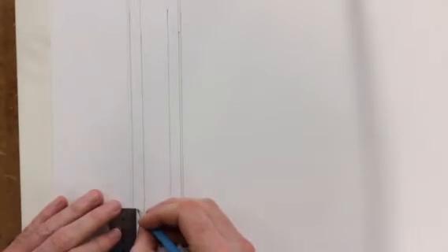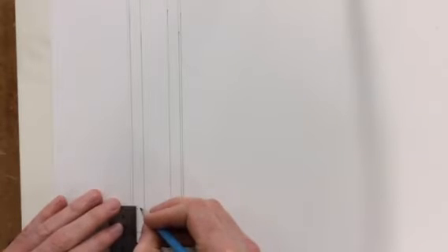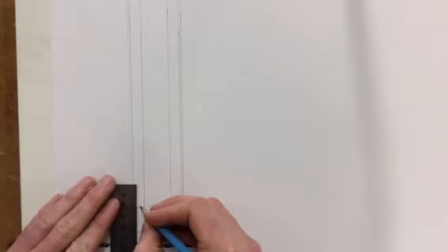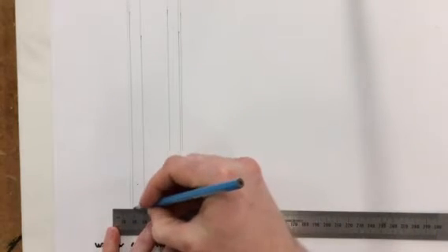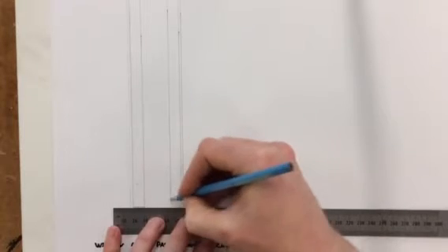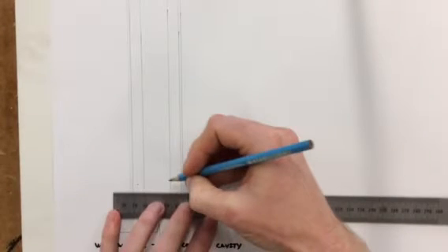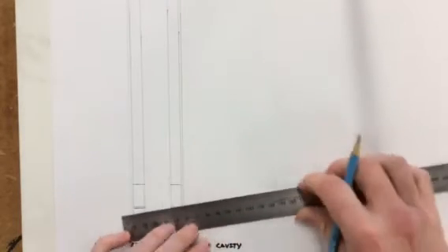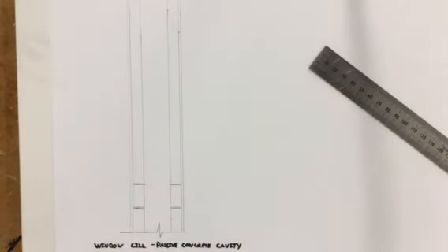Now we're going to mark in a couple of blocks. We're going to start off by marking out 22mm there. I'm going to put 2mm of cement between them, and then another 22mm. I'm just going to bring these lines across to the inner leaf as well, again just using the ruler. And there we have two of our blocks put in.